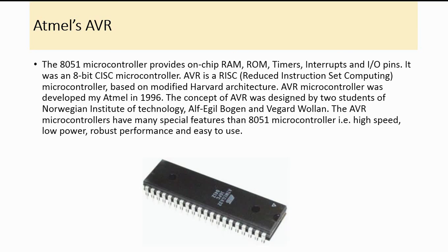But in the AVR microcontrollers, there are some special registers to control the direction of the input output pins, and for giving the output value and reading the input value, there are two different registers, so it makes the operation easy.